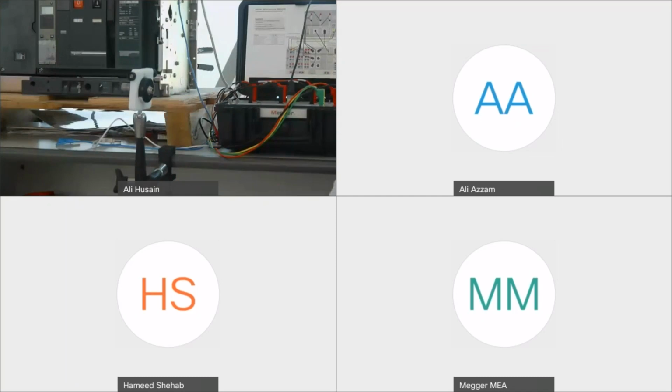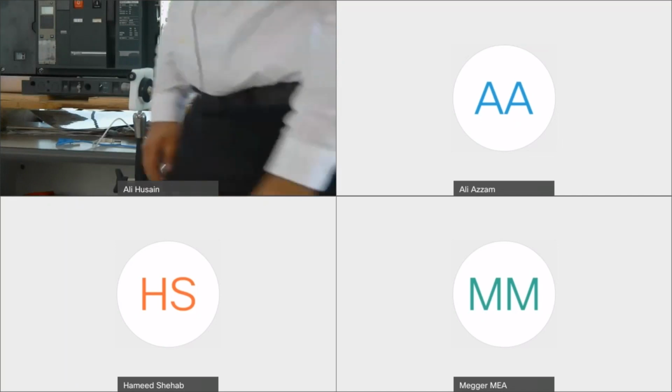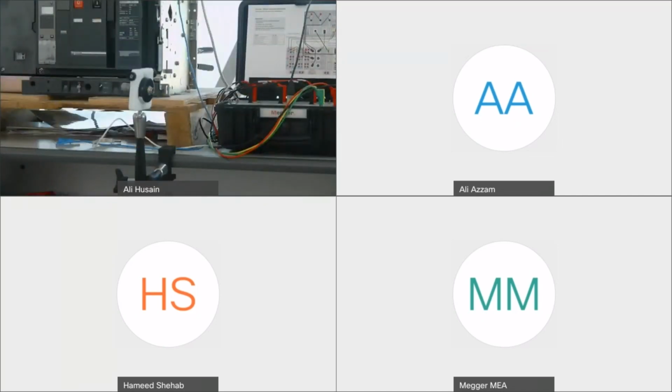We have many other types for mounting, like linear transducers. We have some types for special breakers as well. For example, we have a specific transducer for some ABB mechanisms, HMB and AHMA, where we can do this test as well. So this is just a quick demonstration of the transducer, how it can be mounted.